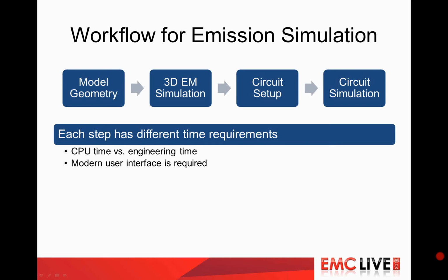So you need a user interface, import and export functionality that allows you to quickly create models. And like I said, the time requirement for these two steps is different, and the 3D EM simulation is typically taking longer, but this is something that can happen unattended. So for example, you can run a parameter sweep of a few different models overnight, and then come back to the office in the morning and use the circuit, which works almost interactively, and calculate the type of results that you want to have. So this is why I propose this coupled workflow of using both the 3D EM simulator and the circuit, just in order to get a very quick and efficient workflow.